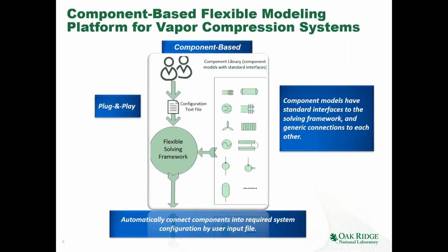In the library, we have heat exchanger models, compressor models, and fan and pump models. All the component models follow strict grammar, and they have a standard interface. The user can select them with a plug-and-play feature, define the connections, and then the solving framework will automatically interpret the connections and group all the selected components into a system.